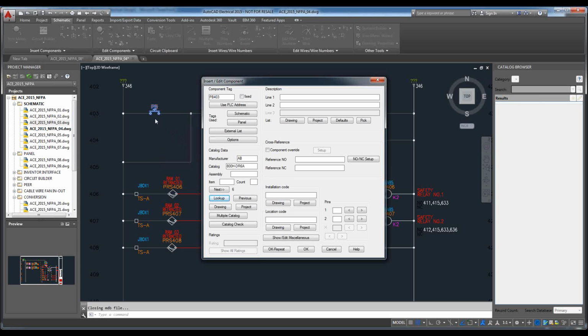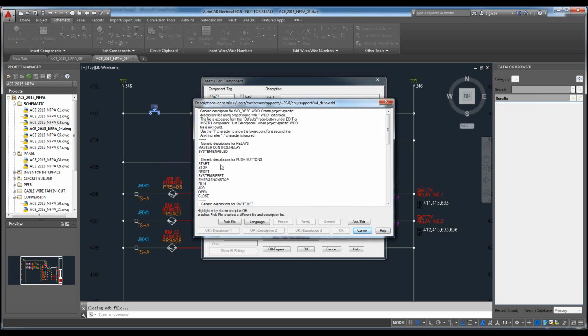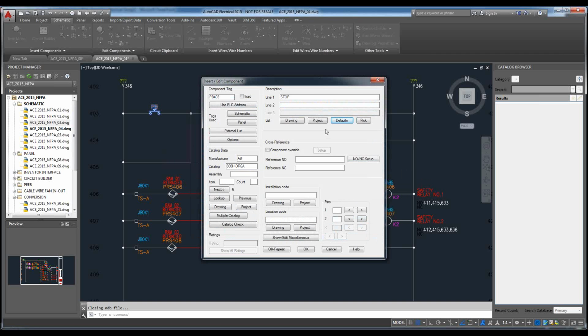You'll notice as I place that on, it automatically trims those wires. So creating that disconnect in that wire, connecting to those pins of that push button, already done for me. Not an extra task, not a trim command I have to go in with something like AutoCAD to create. It's already going to do that for me. So now if I want to look at pulling information, right? Keeping standardization, I can have some default settings, some things to help automate the tedious tasks of typing and error-prone manual entries. I can pull from that information.